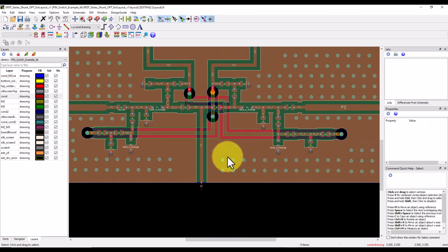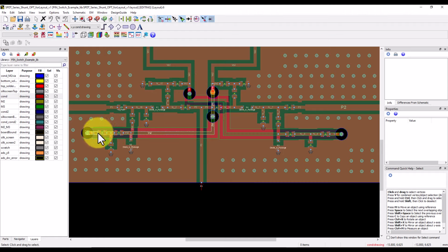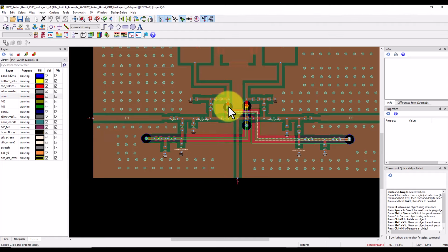And here you can see you have this cross connection for the switch. Remember, we have to pass on the cross connection for the bias supply to maintain forward bias and reverse bias. So somebody might end up doing layout design something like this, where you have a long interconnect going between these bias lines to create that crossover.